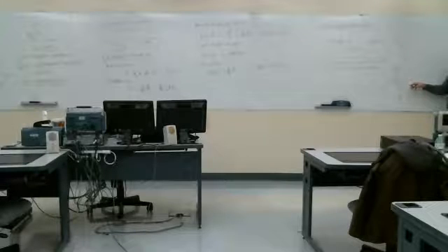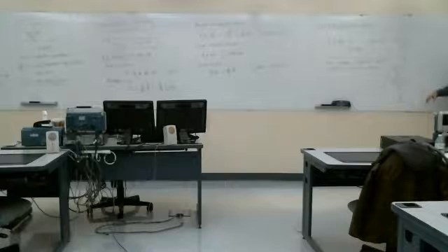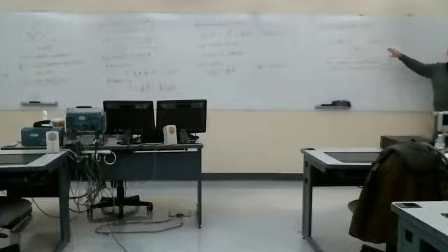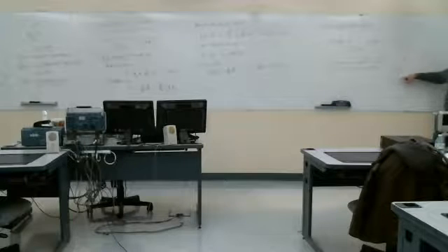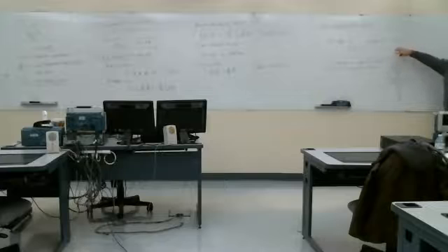We know that there's no current flow actually through this dielectric material. So with my surface like this, with a capacitor, here if I have my surface here, I get this result. But with my surface actually going through a capacitor like this, there is no current here, and so I know that this no longer appears to be true, or something's wrong with my equation. Now, in the DC case or static case with a capacitor, there is no current, and the right-hand side is 0 here, and it's also 0 in the capacitor.